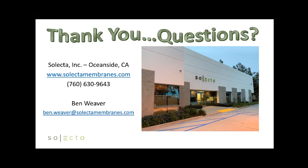Gracias por la presentación. There is a question, Ben, can the membranes be washed with acetic acid? Yeah, absolutely. Acetic acid is a common cleaning chemical. So what I can do is send Alejandro all of our cleaning recipes. There are about 4 or 5 different recipes depending on the degree of fouling and the type of foulant that's used in e-coat. So I can send those to Alejandro and he can distribute them to anyone on the call.